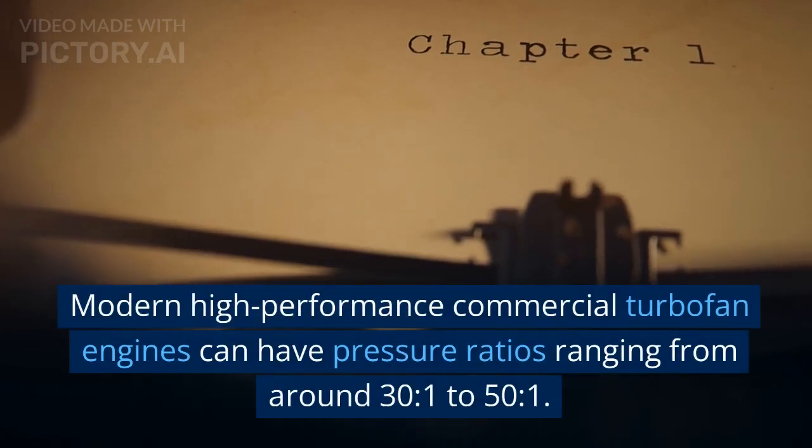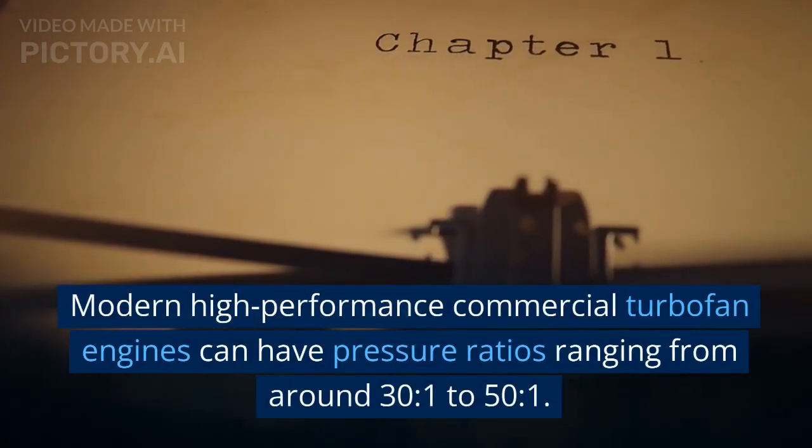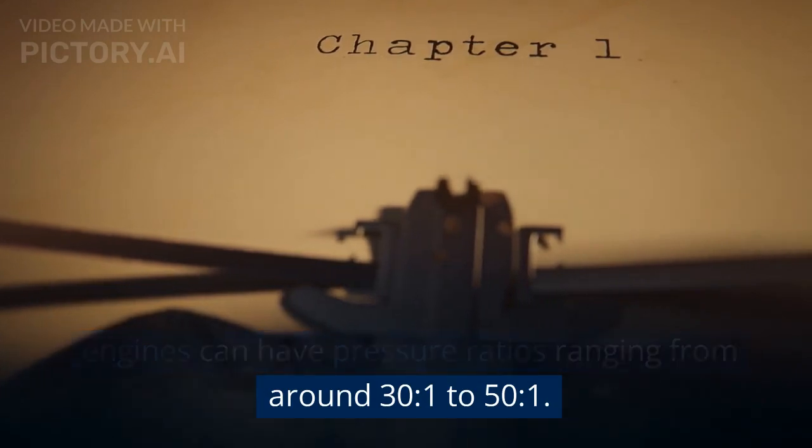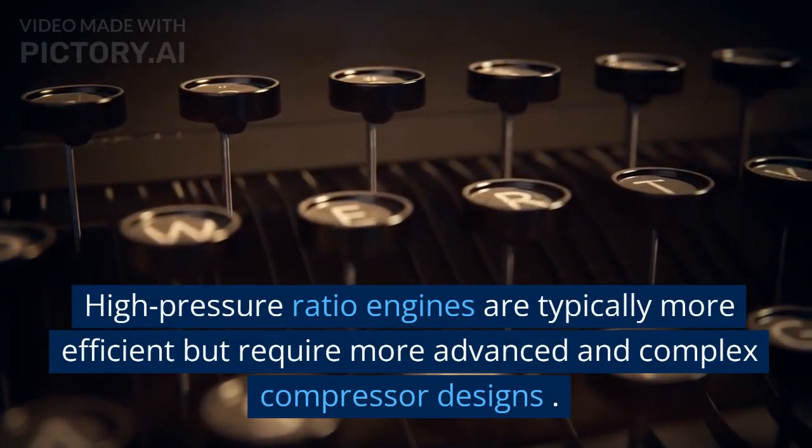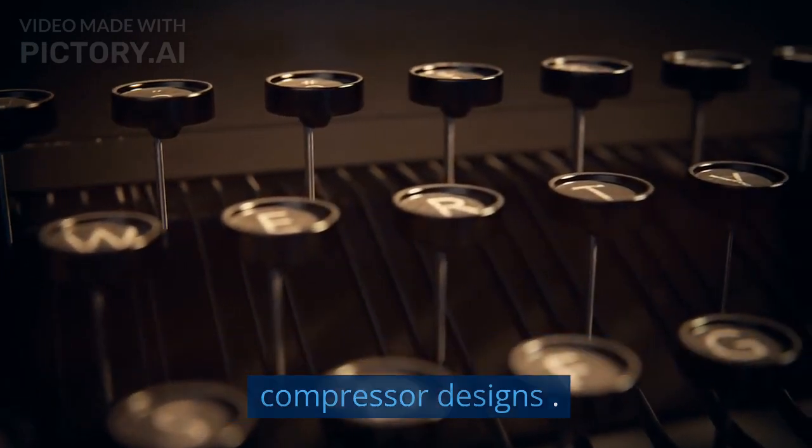Modern high-performance commercial turbofan engines can have pressure ratios ranging from around 30:1 to 50:1. High-pressure ratio engines are typically more efficient but require more advanced and complex compressor designs.